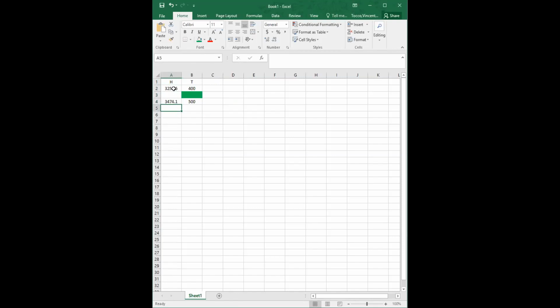All right, so I need a convention. I'm going to color this in, let's say, orange to tell me that this is data that I get. And I'm going to say that the blue one is going to be the point that I want. So the point that I want has to be in between, which is why I arrayed it like this. The enthalpy that I want to calculate with is 3373.7.